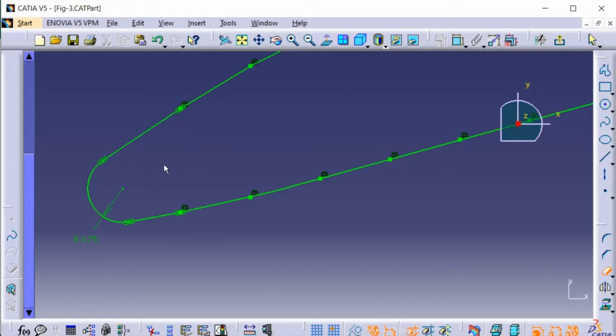Now you can see the circle has been constrained and the leading edge has been generated. So this is how you can generate the aerofoil if you are short of the coordinate values. Here also we have to decide which parameter you have to control: the radius, the chord, the distribution, like I have said in the earlier case. Accordingly, you can constrain this arc.